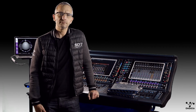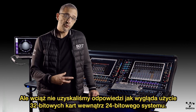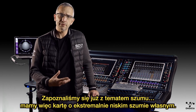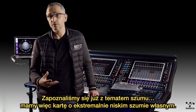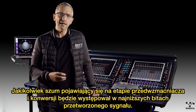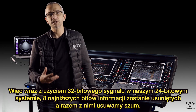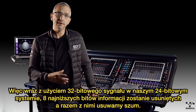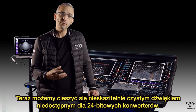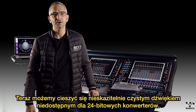We still haven't answered the question of how we use a 32-bit card with a 24-bit system. Again, the answer to this is pretty simple. We've talked about the noise and how we've designed a card with incredibly low noise floor, but any noise present as part of the preamp stage and 32-bit conversion is in the lower bits of the digital signal. So in order to use our 32-bit signal in a 24-bit system, we discard the bottom 8 bits. And this is, of course, where the noise is. We have our pristine 24-bit signal with a significantly lower noise floor than previously possible with 24-bit converters.